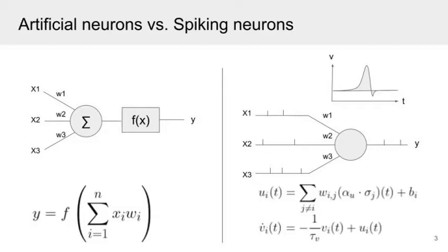A spiking neuron integrates the input current over time until a voltage threshold is reached. At this time, the neuron will send a spike through the connections called synapses to a postsynaptic neuron. The voltage potential of each neuron is calculated at each time step, which uses a lot of power when simulated on CPUs or GPUs. But a few hardware accelerators have been developed to optimize speed and decrease latency and power usage. One of these is Intel's neuromorphic research chip Loihi.